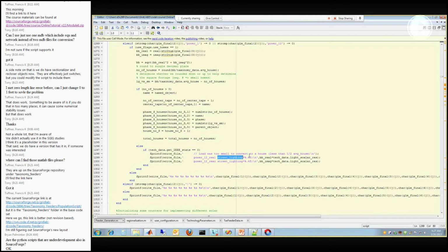When you allocate the load across the feeder from the peak load study, there are residuals left over that get populated. Maybe there's a single meter way down on the feeder, and that's the residual left over from the algorithm, so it gets assigned a very small value. Rather than trying to figure out what each of those are, especially on these very broad models, once you get less than one half the average house size, we just assign streetlights to it.